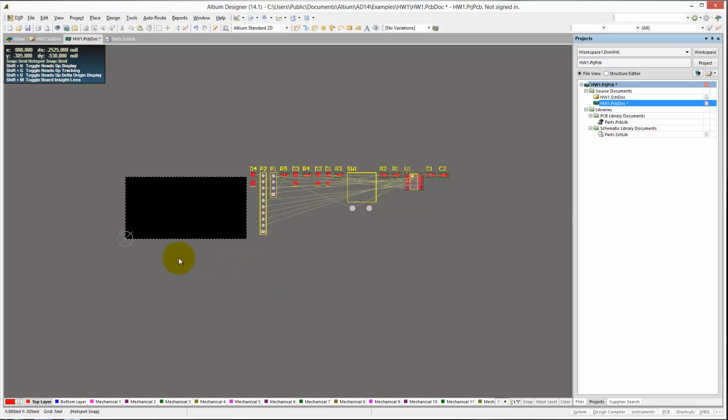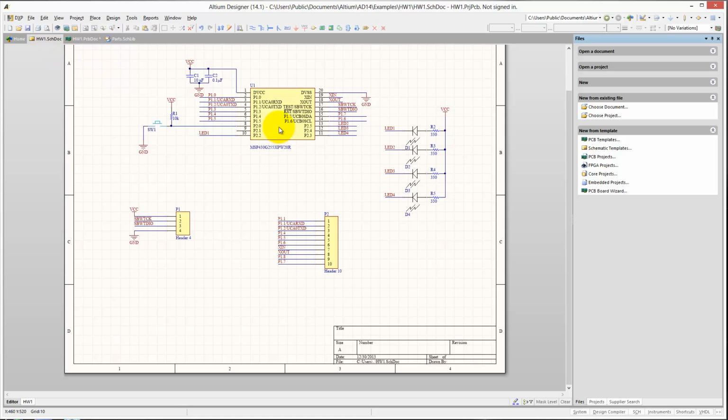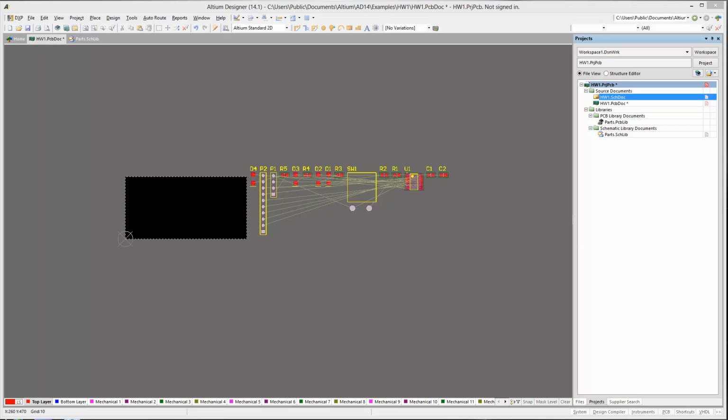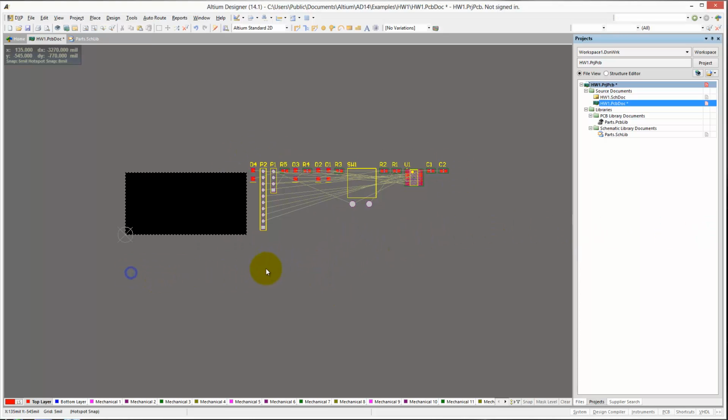Alright, next step is to arrange these components on our PCB such that we have a good layout and the routing of the different wires and connections that we see here becomes easy. A very good help is if you have your schematics right next to you. So either print this out, or what I do is grab the tab and pull it out onto a different display on the side so that I have a reference to look at on where the connections go and what the different signals are.